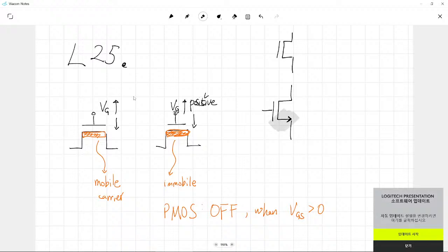And what is it? Is this the source or drain? You can easily understand that in the case of an NMOSFET, this arrow was attached to its source. Then if we consider our PMOSFET, we also follow the same convention. Source should be denoted with our arrow.